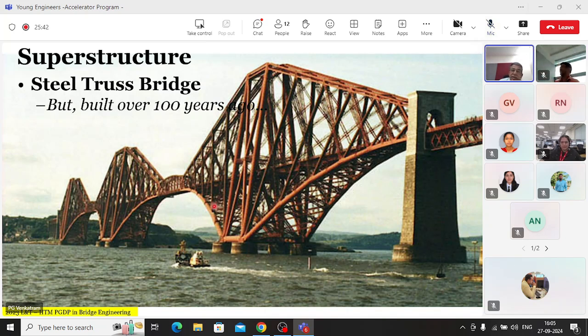So basically, it's a cantilever bridge assembled from the pier outward, and finally a bridging suspended span is lowered there to cover the gap. So this is a cantilever bridge in which the traffic is going through the truss. So this is what is called a semi-through. For a major portion of it, part of the truss is below and part of the truss is above. And of course, the suspended span is a classical through truss.